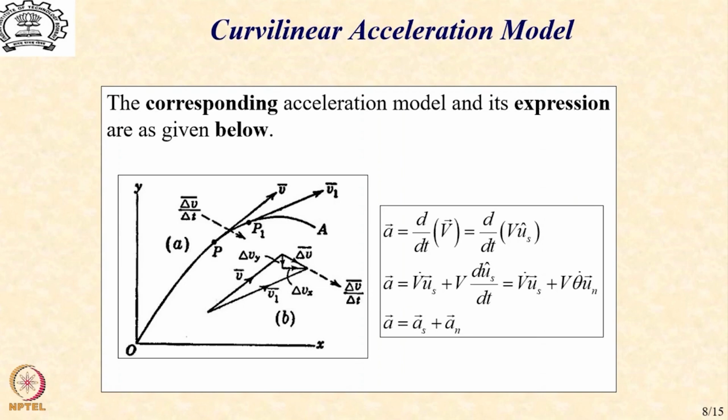So now we have two acceleration components, as, which is v dot, that is along the velocity direction, and another acceleration an, which is normal to the velocity direction. So we realize that in the context of the trajectory coordinates s and n, the vehicle now has two accelerations, one along the trajectory and one normal to the trajectory.